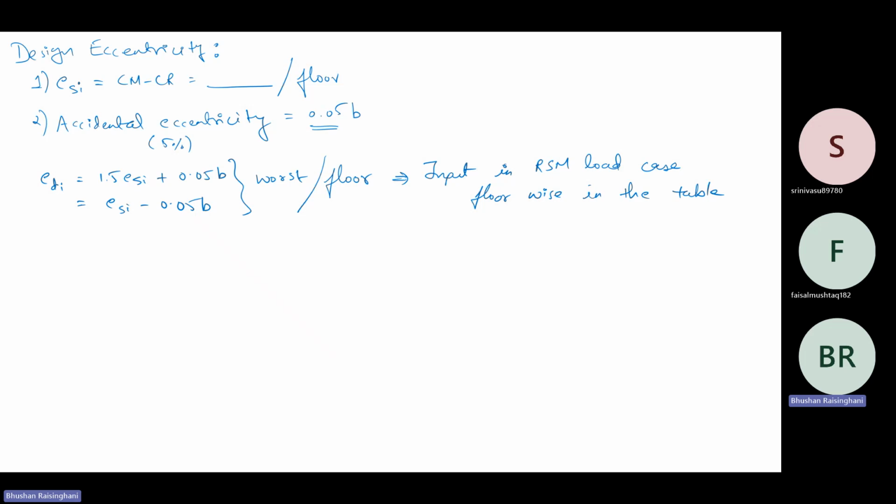You have to distribute the stiffness well proportioned in the building, not just concentrated at one point. And your time period has to be regulated in two directions. Also, the time period of the torsion mode should be in the third mode.